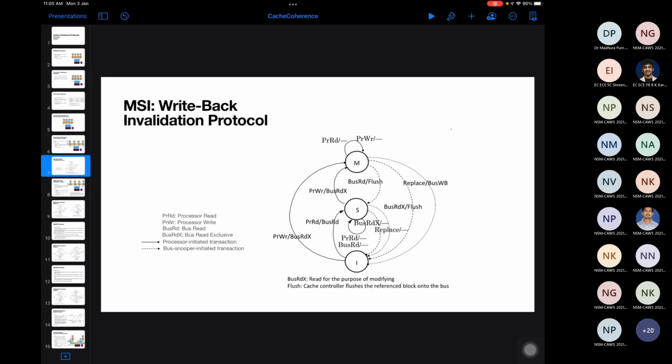Remember, this cache coherency protocol itself is an overhead to the multi-core system. We require this to ensure that the data is coherent. But to ensure the coherence, we are going to have all these extra transactions and so on, which actually eats away the memory bandwidth. While we are using the bus, the other cores may not be using the bus for useful operations and so on. So your overall efficiency of the multi-core system is going to be degraded if you are going to use these coherency protocols. But of course, correctness is the important thing, first and foremost.